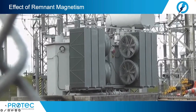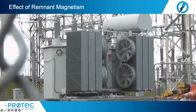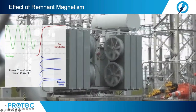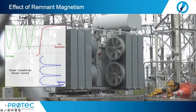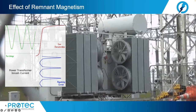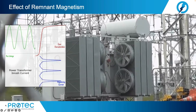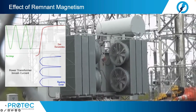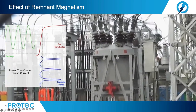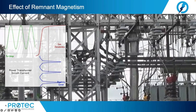Now, remnant magnetism can cause various problems. Now, these problems include high amplitude of inrush current at startup. Now, inrush current is a form of overcurrent that occurs during energization of a transformer and is a large transient current which is caused by part cycle saturation of the magnetic core of the transformer.